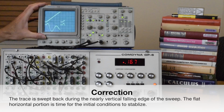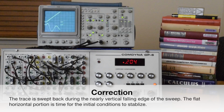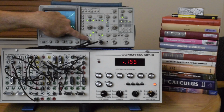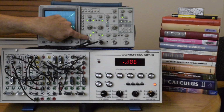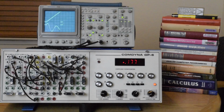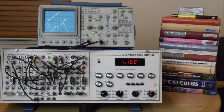But that's actually what is being inputted into the oscilloscope. The way we look at it in the oscilloscope is to use this signal to deflect the x-axis across, the time axis. Sorry, I said y-axis. That is channel 1, or x, in x mode. And then channel 2 is what we use for the y-axis deflection. So that's the raw signals that the oscilloscope is looking at.